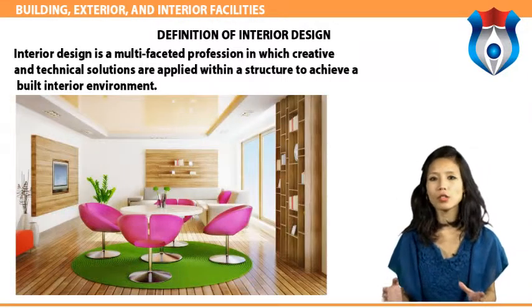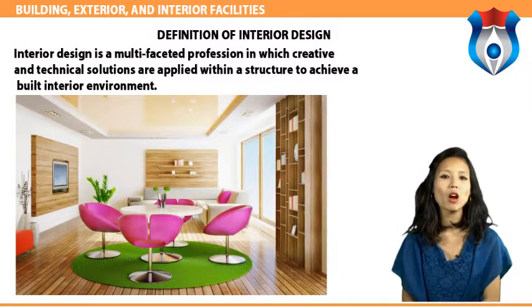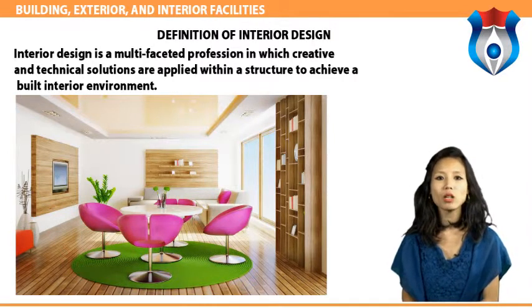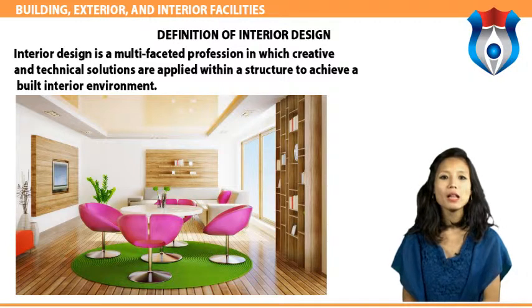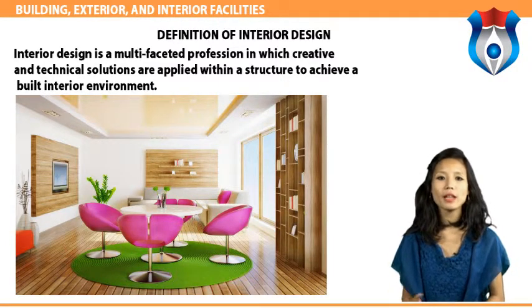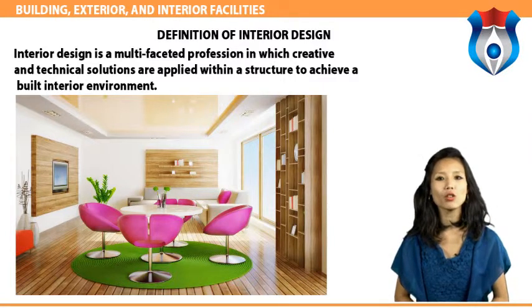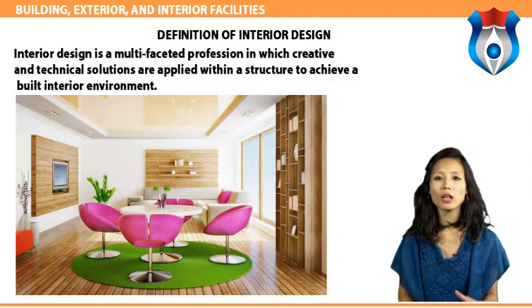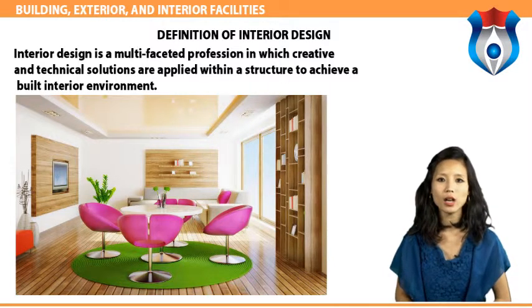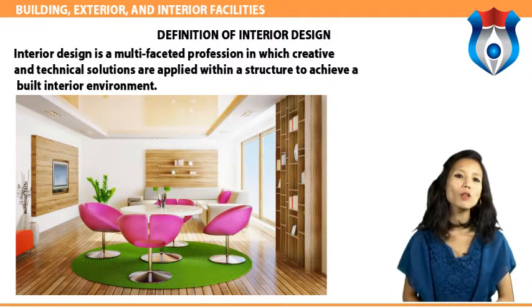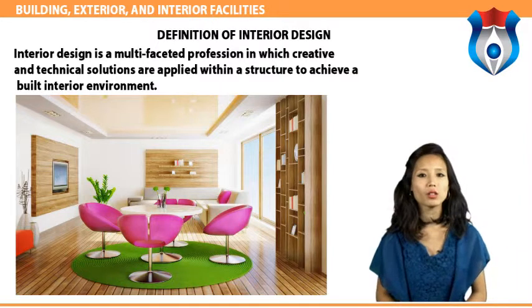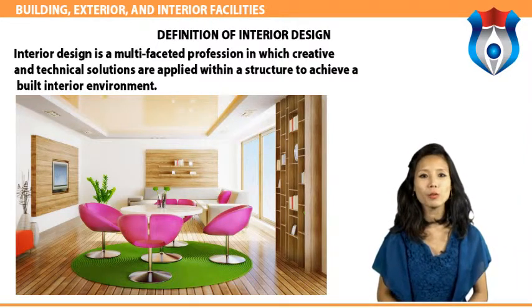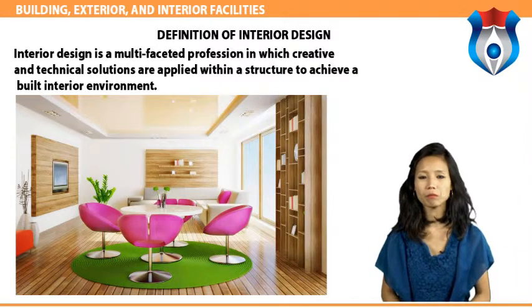Selection of colors, materials and finishes to appropriately convey the design concept and to meet socio-psychological, functional, maintenance, life cycle performance, environmental and safety requirements. Selection and specification of furniture, fixtures, equipment and millwork including layout, drawings and detailed product description, and provision of contract documentation to facilitate pricing, procurement and installation of furniture.